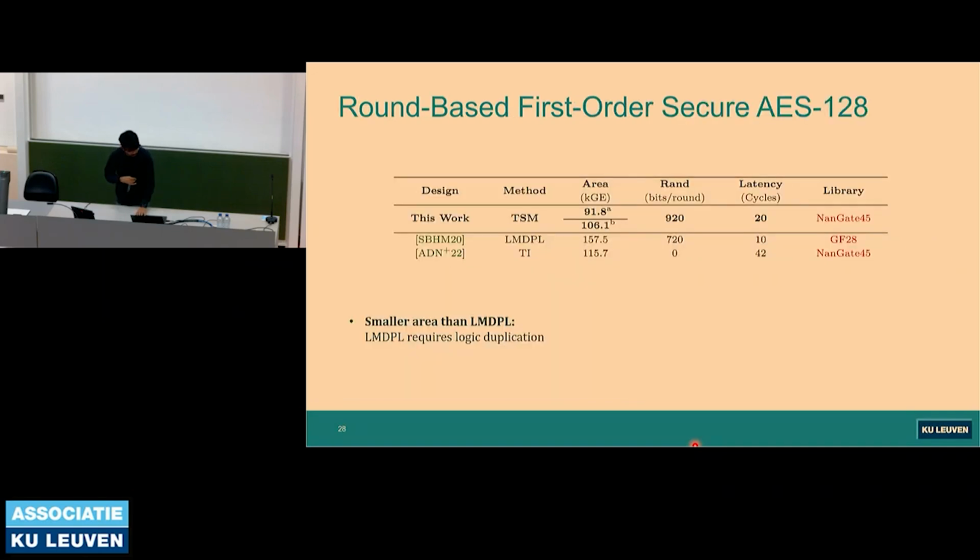Now, we build a full AES with this. So we have an S-box, and then we instantiate 16 for the round function and 4 for the key schedule. And then it's all masked. Key schedule is masked, round functions are masked. So it's 10 rounds in total, so 2 cycles per round, and then you have 20 cycles in total.